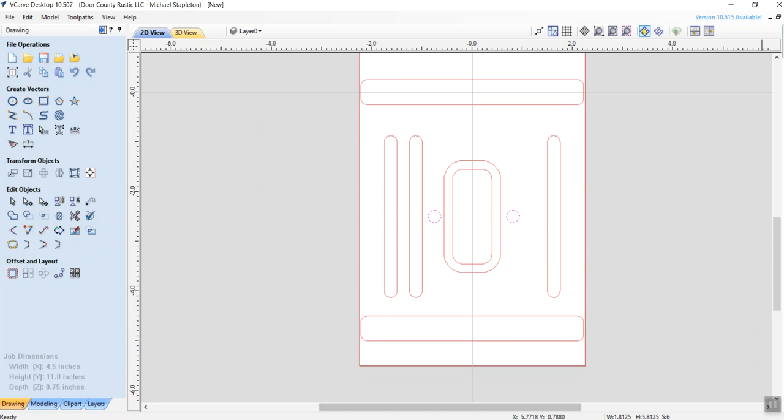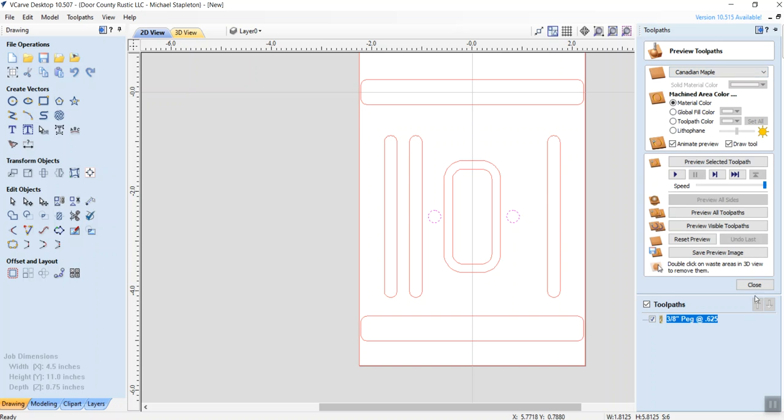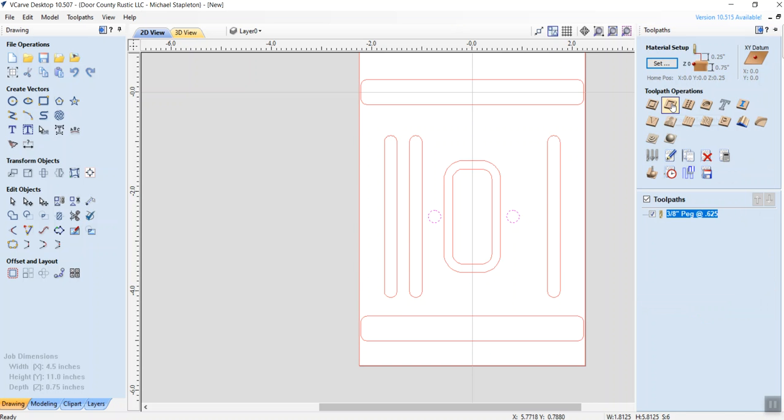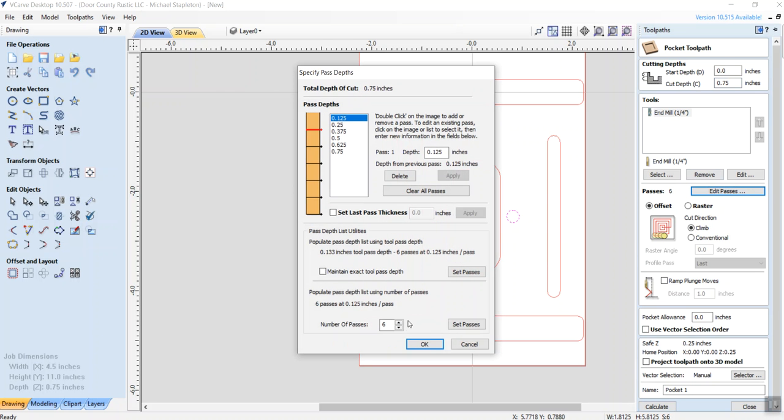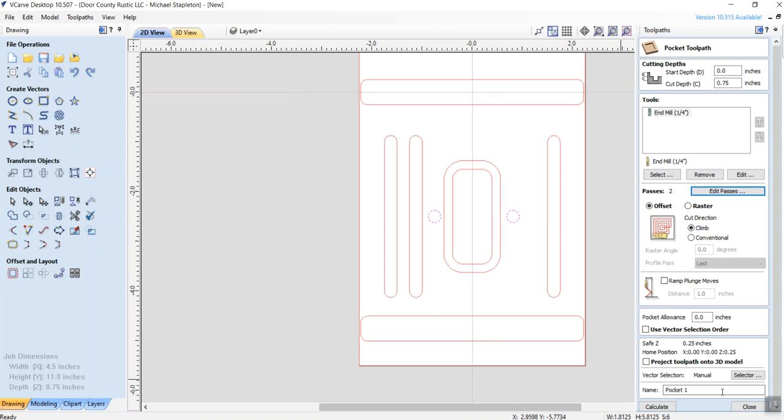Those are all 1/4 inch holes. So I can click on here, do the same thing on this guy here, and then those I want to go full through because they're peepholes, so I'm going to do 0.75. And then again on passes, that's a 1/4 inch bit making a 1/4 inch hole. So I'm fine with 2 passes. It's just going to basically go straight down through the PVC. And then those would be all 1/4 inch holes at 0.75.